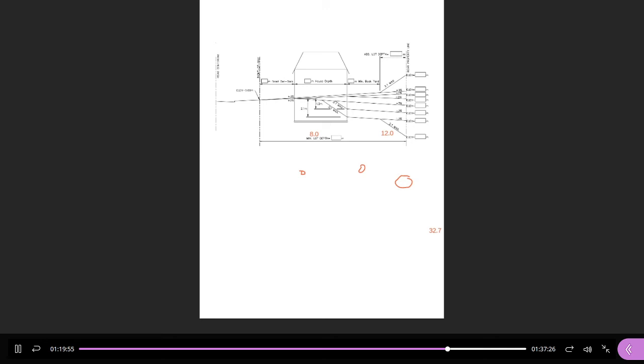So these are the thresholds. These numbers, you need to know what these numbers are, because what you're going to do after assignment 3 is go to each lot line and measure the vertical difference between the front and the back. And then you'll fall somewhere between all of these numbers. You could be higher than 2.56, then you know you have a front draining lot with a full slope and a little bit of a wall. You could be lower at the back by more than 4 meters, and then you know you have a full walkout with a minimum usable backyard, a full 3-to-1 slope, and then a retaining wall. Or you could be somewhere in between as a scenario.